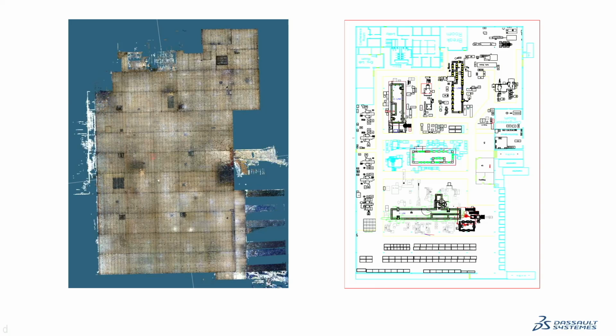So right now the workaround for that, if you want to keep running PDM and bring stuff in here, is this. We work with some customers. What they do is they pack and go out that assembly, and then we bring it in. And if there are changes, they save out the parts or sub-assemblies that changed, pack and go those out, bring them in, and then we can replace them that way.